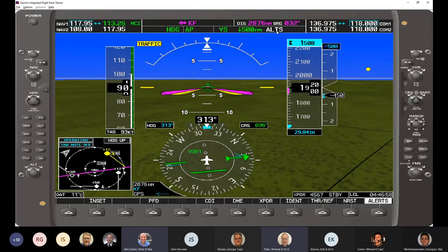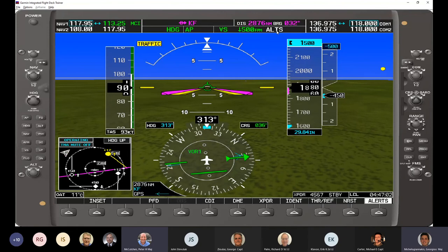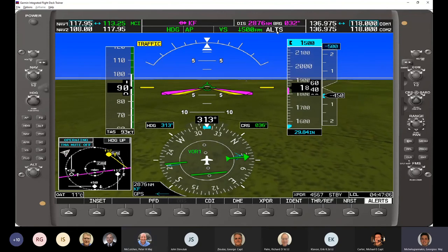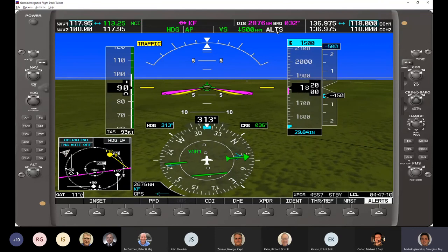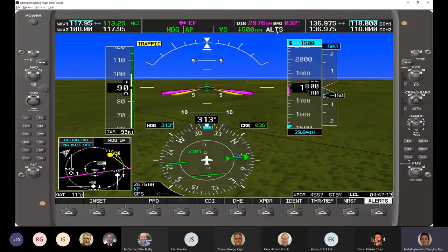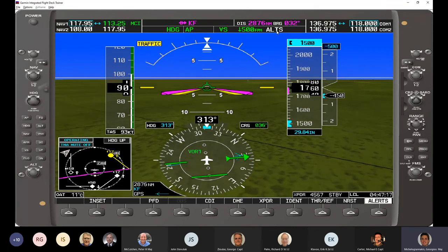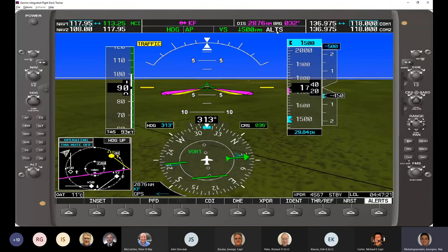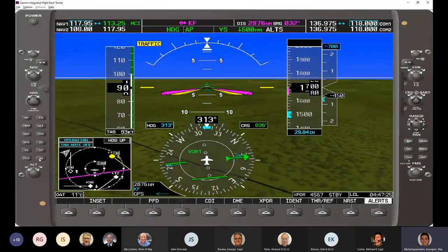George, this might be helpful to set a pattern altitude on descent. Maybe, yeah. If that works for you, that's great. You can use the altitude bug for the pattern altitude of the airport you're flying to. Absolutely. It's a really helpful reminder. Even if you don't use it for the flight director, it's a reminder. Like you can use it to remember the altitude that you were given. All right. So now I'll speed it up.